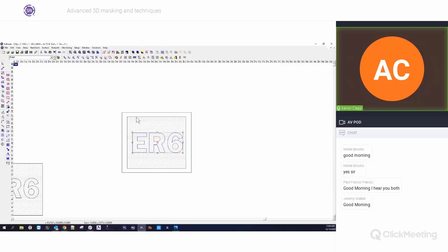If I shift click the relief, we notice that the letters don't really change, because, again, the relief does not count towards a container. That's why it was important for me to draw this extra box on the outside. Now this box could go anywhere. It could be farther out or further in; it just depends on your use case scenario. So now when I highlight this external box, I get my red letters.